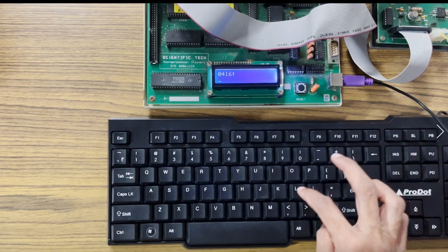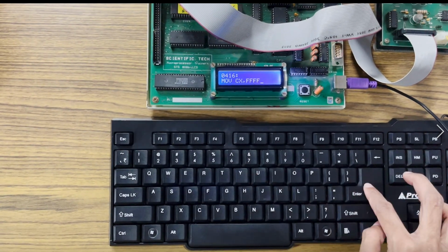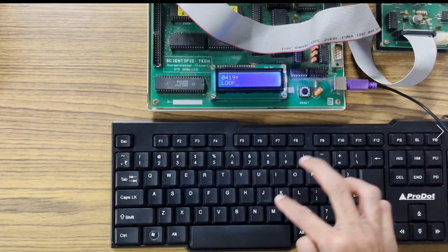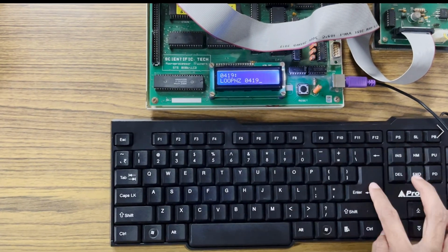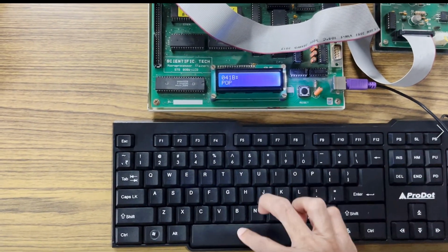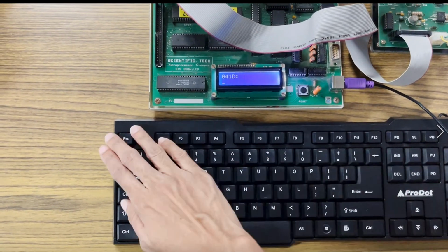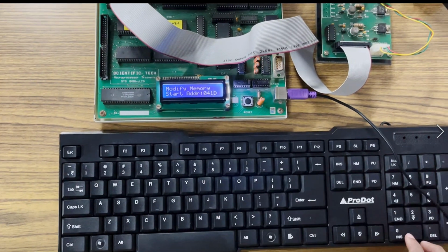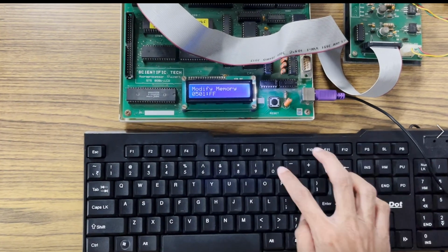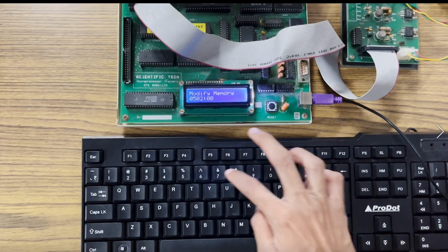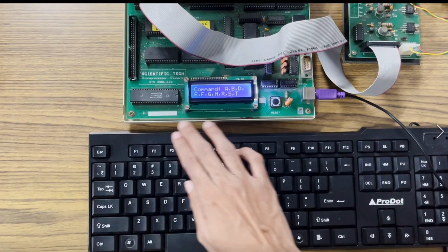So in the delay program, we'll push the value of CX. Then we load CX with double F, which is the max value. Then we perform a loop in the same step. That is the delay that is generated between the consecutive steps. Then after the delay, we pop out the value of CX and we return from the call. Now loading the values at 0500, which is 0A, 06, 05 and 09. Then we'll run the program.